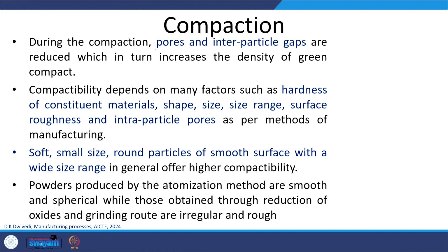During the compaction, the pores and the gaps between the interparticle spaces are reduced, which in turn increases the density of the green briquette. This happens due to the collapse of the pores and voids between the powder particles. Compactability also depends on multiple other factors such as the hardness of the constituent materials, their size, shape, size range, surface roughness, interparticle pores, etc., as per the method of manufacturing.